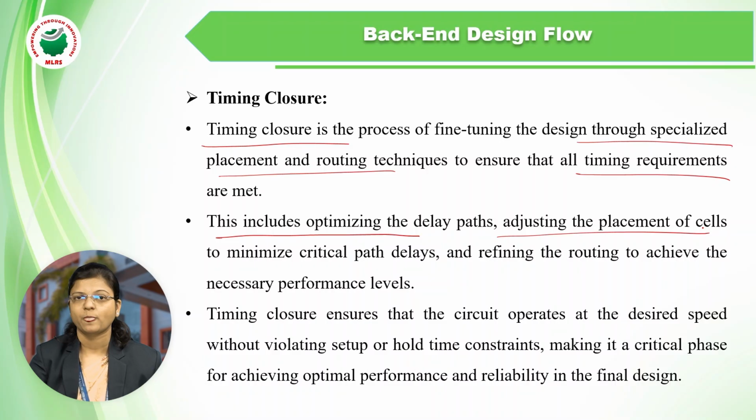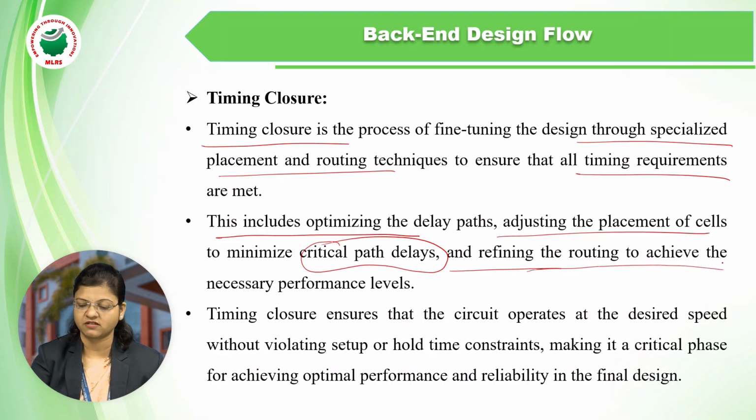So we have to adjust the placement of the cells to minimize the critical path delays. Critical path is nothing but the longest path without any delay. So we have to minimize the critical path by proper timing closure. And again, we have to refine the routing to achieve the necessary performance level. Then what will timing closure do?